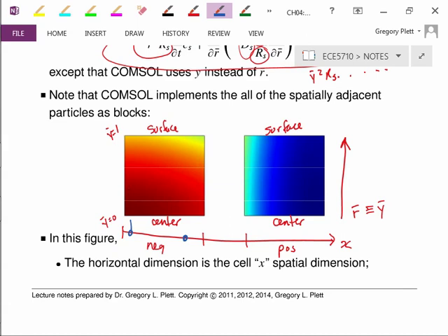And what we're seeing is the negative electrode is preferentially discharged through the region closest to the separator, but there is some discharge happening everywhere because there is a color gradient. It's not uniform. Therefore, some lithium is coming out of every X location, but more is coming out of the X locations near the separator as I'm discharging the cell.